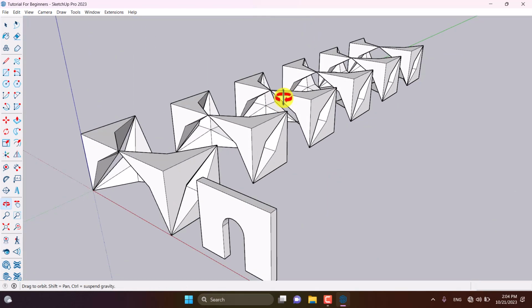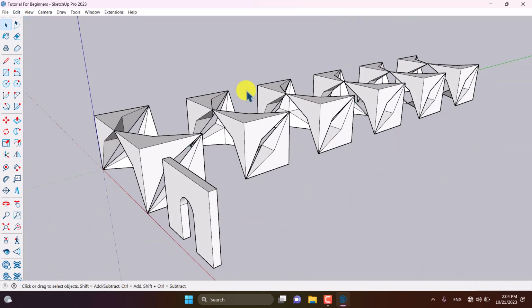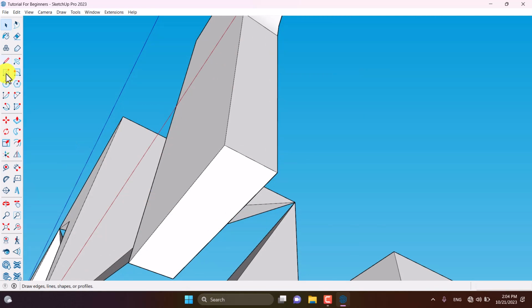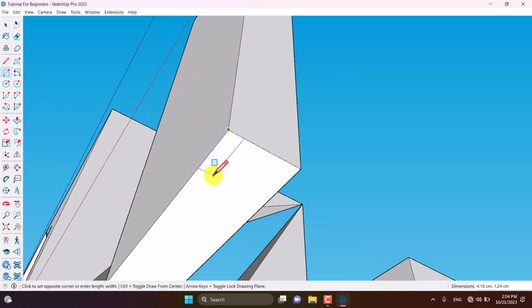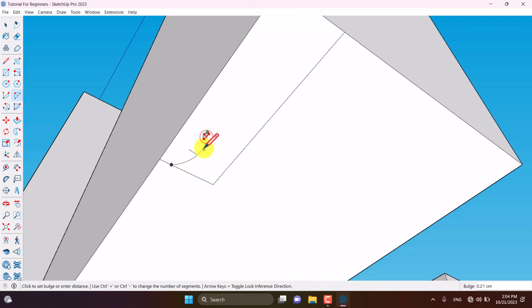You can hold the scroll on your mouse and move your cursor, and the result is something like that about orbiting. If you want to use it manually, you can select orbit from the left side in the navigation bar for reorienting the camera view. So I'm going to orbit my camera shot in here and add some type of special details for my 3D interior job. So I'm going to use the 2-point perspective in here like that, and some type of complicated shape like this near to the classical design, but not actually something like it.